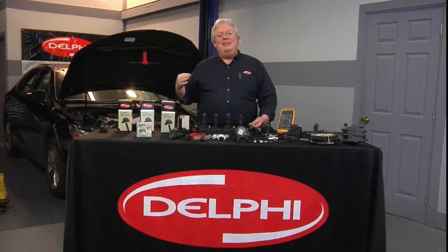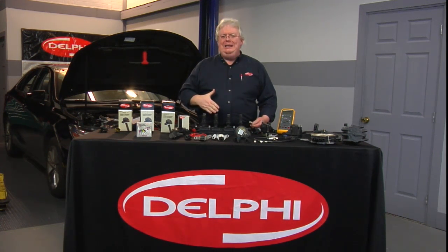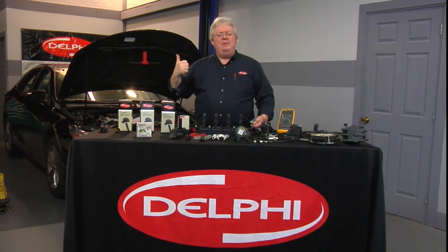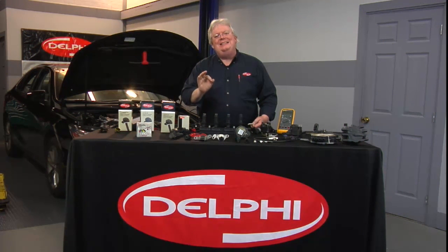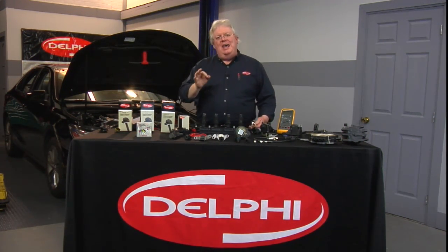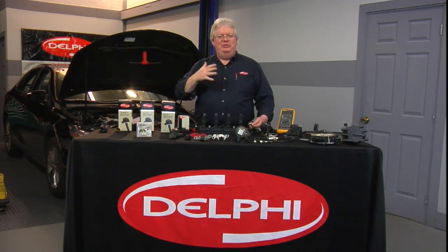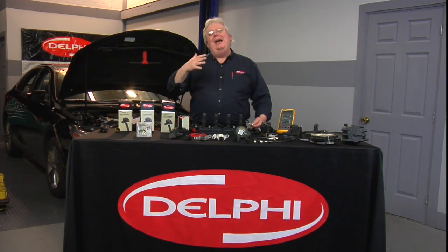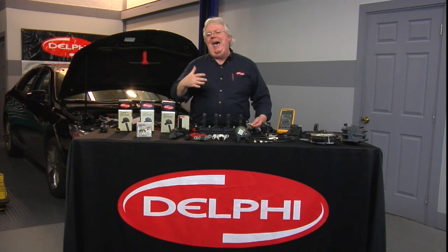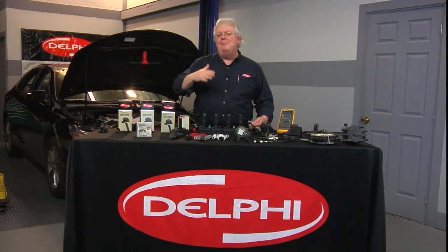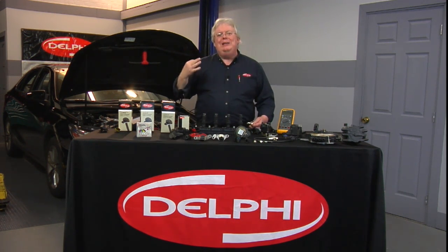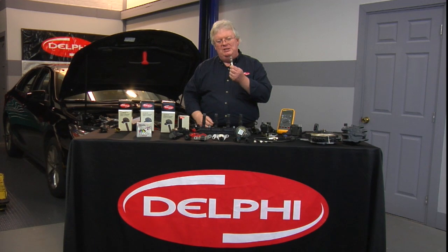So when the O2 is low voltage, lean, trim goes positive, but not as positive as a lean misfire. So let's say an injector's not working, that kind of a lean misfire can be 20, 25 positive % on fuel trim, whereas an ignition misfire might be half of that. Both will run the trims high, positive, but the fuel trim will be much higher when it's a true lean misfire as opposed to an ignition misfire.